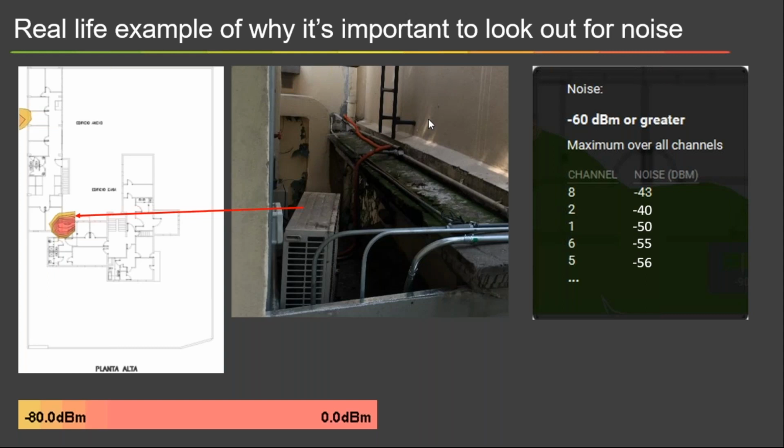That's your clear channel assessment telling you that, okay, it's your turn, you can speak. Exactly. It's just too much noise. Minus 80 dBm, minus 85, that's tolerable, but minus 43, that's not. Just for Wi-Fi, ideally, minus 82 is the second level. So you want to try to avoid something that's going to generate more noise than minus 82, ideally. Yeah, I agree. Okay, let's keep moving.